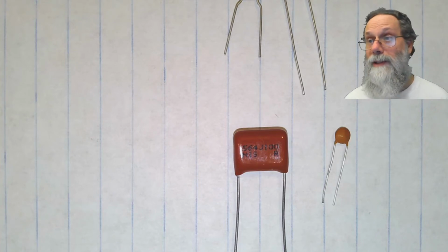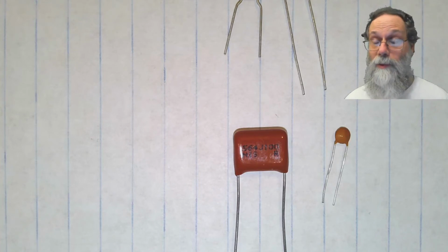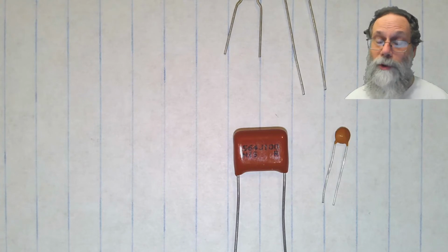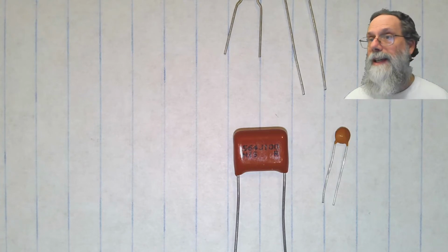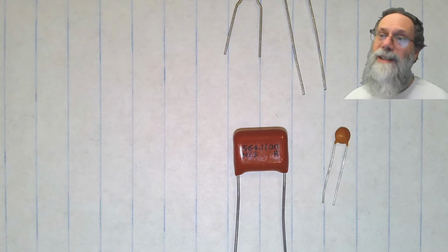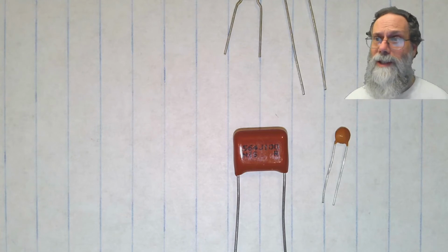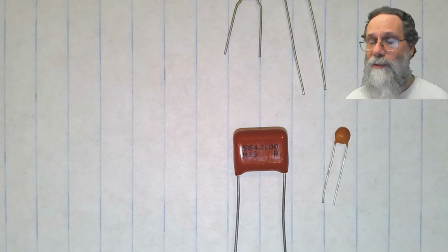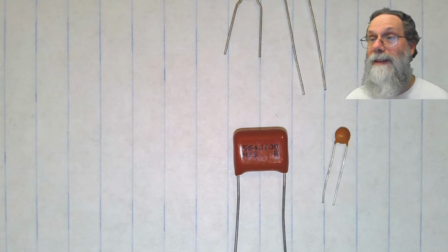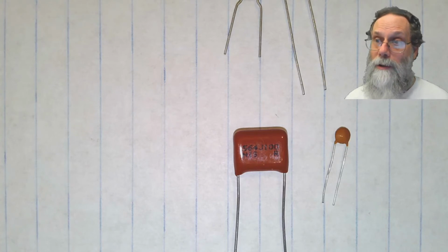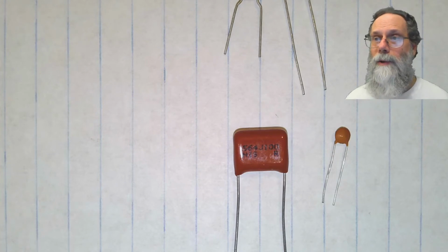Now, the ceramic insulator has some disadvantages as well. It's harder to control to get a precise value. It's temperature sensitive. It's also somewhat voltage sensitive, so that the capacitance isn't really the constant you would like it to be with a ceramic capacitor. The advantage for ceramic capacitors is that they're very, very cheap and very, very small. So they get used a lot when you don't need to be super precise about the capacitance.